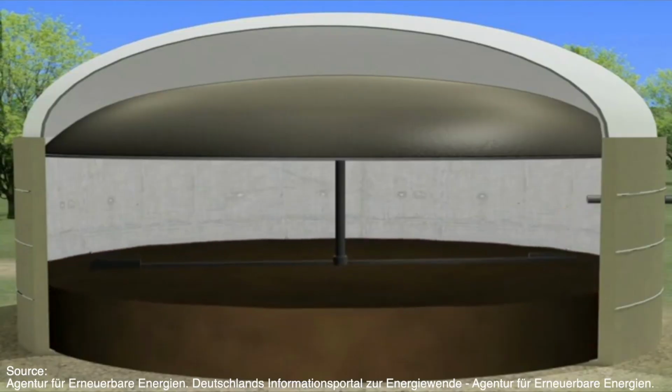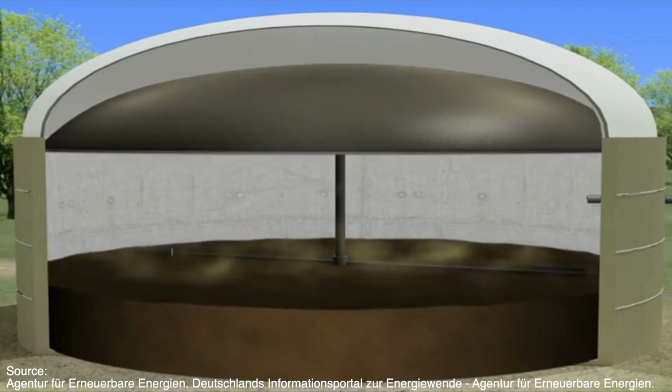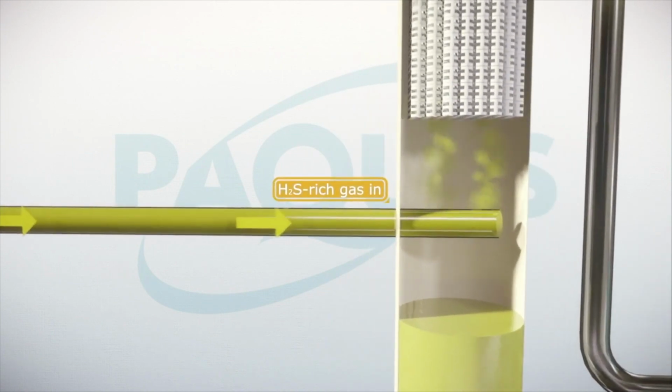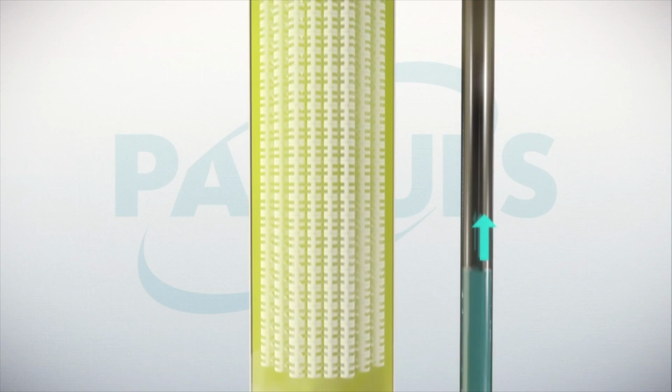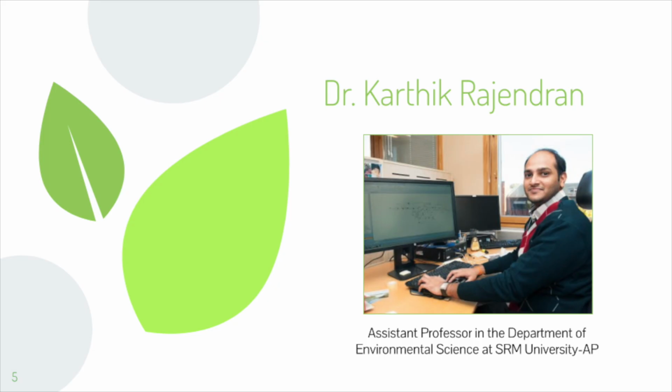Then the sludge is pumped on a daily basis into the reactor, where an optimal residence time will allow for good conversion to biogas. The produced biogas is then sent to an absorber in order to remove impurities such as hydrogen sulfide, which smells like rotten egg and is very toxic and corrosive, and must be removed to the highest extent possible. As Nicholas mentioned, our system will support a wide variety of substrates.